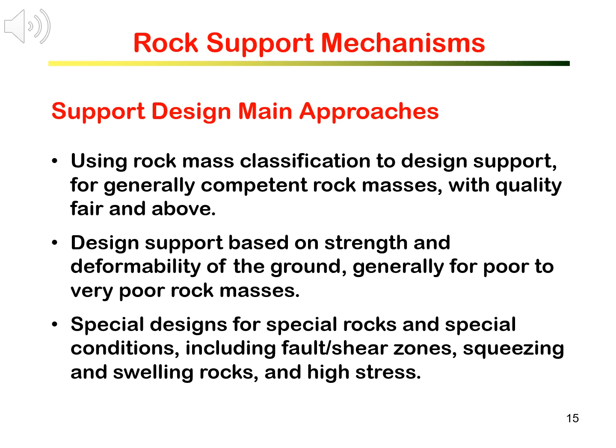We can design support based on strength and deformability of the ground, generally for poor to very poor rock mass quality. That is, generally for highly fractured and highly weathered rock mass. Special designs are used for special rocks and special loading conditions, including faults and shear zones, squeezing and swelling rocks, very high stress, and very shallow rock covers.